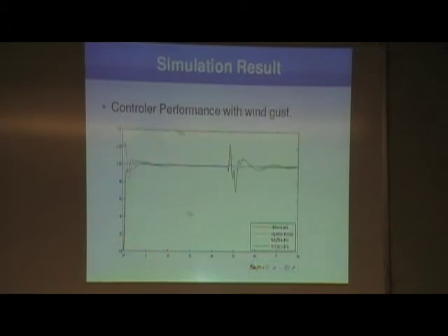More advantage can be shown later in this figure. For this one, we are trying to simulate a wind gust. When we are flying unmanned air vehicles, it's going to be a changing world. It's not going to be that stable. So here we simulate the circumstance that, assume there's no wind before 5 seconds, and at 5 we get a wind gust that lasts, probably 4 seconds.